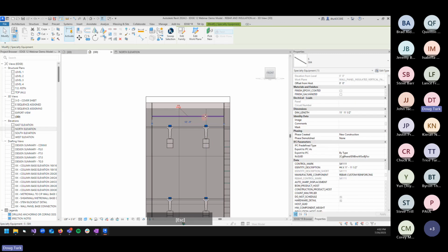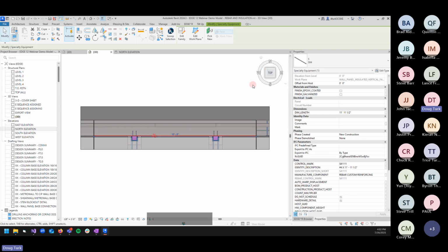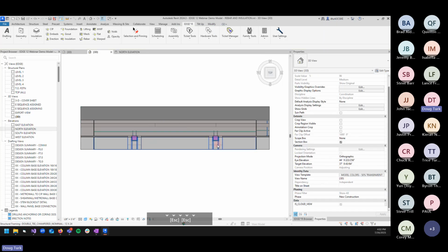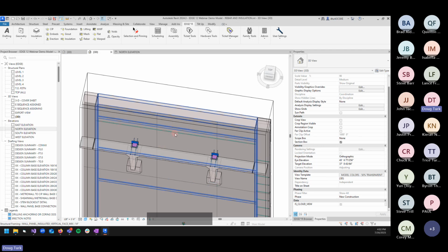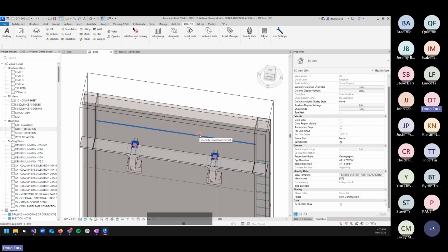However, we have seen and acknowledged that Revit has come a long way with their rebar, and we are working in the laboratory on different opportunities to match what they're doing with some automated rebar placement. This is a super simple version of what you might do: you host the rebar to the face that the cover's on, bring it in, and stretch it to the correct locations.